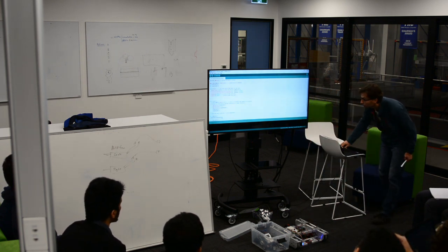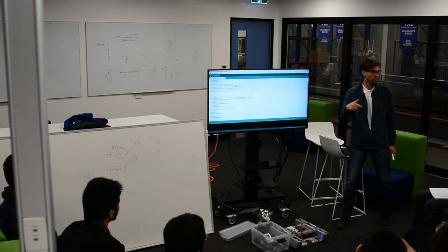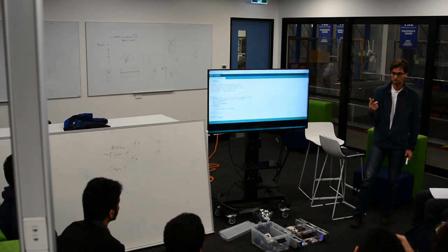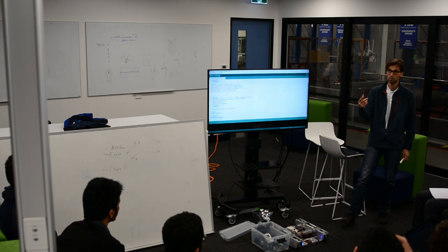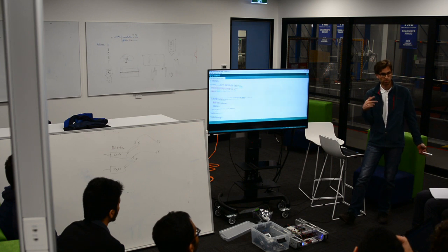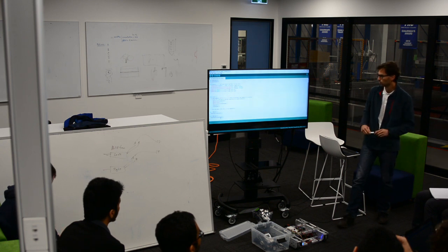And then did I put anything on ISR right? Yeah, the same thing. Ultimately, this variable called count right is going to do the counting of our position. It's going to represent how many ticks forward we are, how many ticks back. We don't know right now how many ticks will be in a meter, but we could figure that out, because we can either experimentally determine it, or we can look at the data sheet for the motor, and it'll tell us that there are 240 ticks per revolution or something like that, and then whether it's geared or ungeared, and we've got a 40x gearbox or whatever it is. For now, we're not going to worry about it.